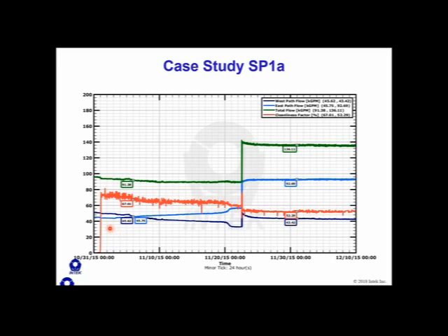I think you would expect to see the cooling water come up with one pump and stay flat, and when the second pump comes on, go up and stay flat. I think you would also expect that the cooling water flow rate per path, when you turn on one circulator, should come up to a one circulator flow rate and stay flat. And same with the east and west path, they should come up and stay flat.